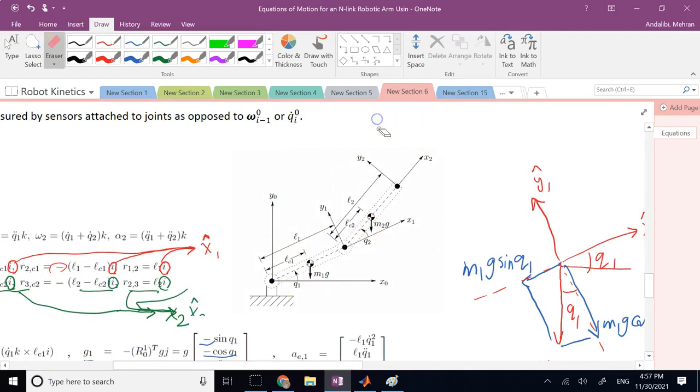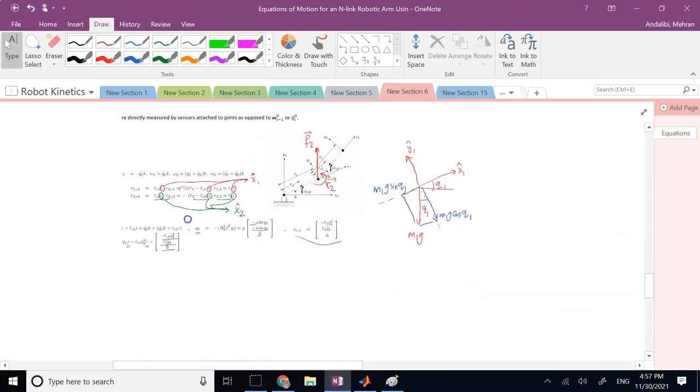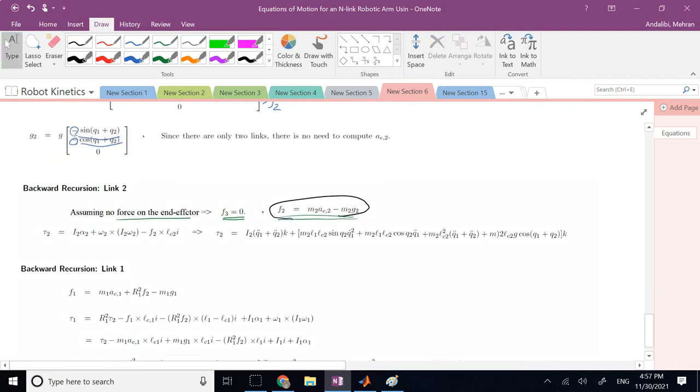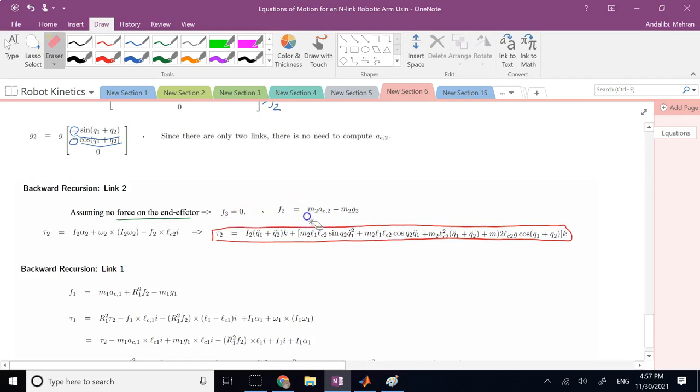So now you can calculate how much torque you need at that joint. So tau2 and then F2. You found both of these in this step using equations 5 and 6. So this is going to be your tau2, quite long. And as I said, this is going to be your F2.